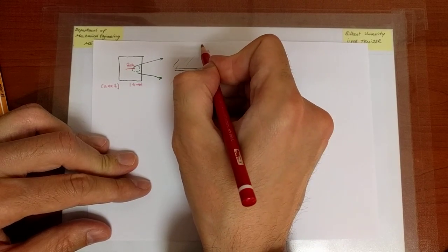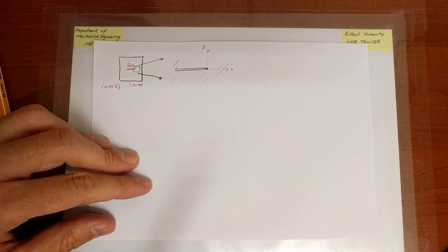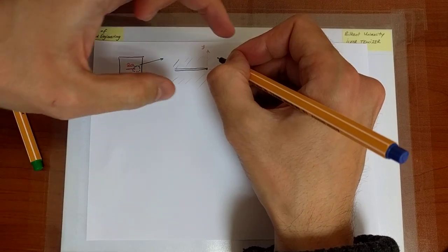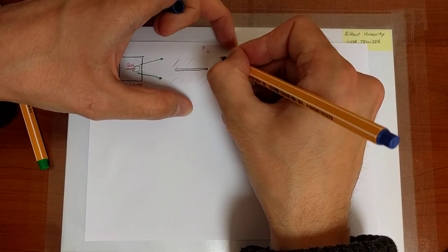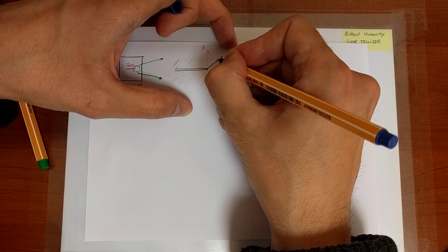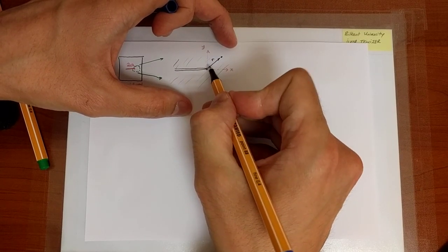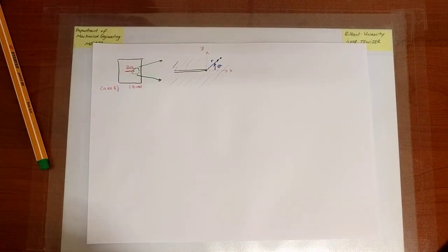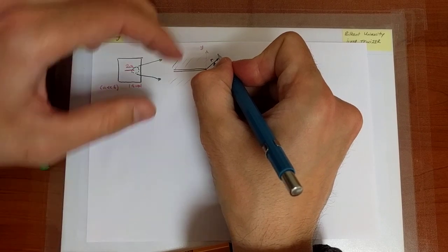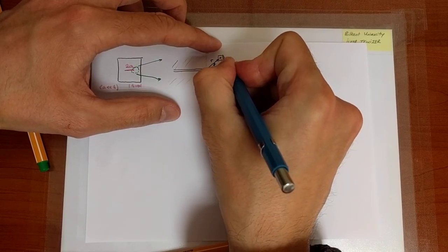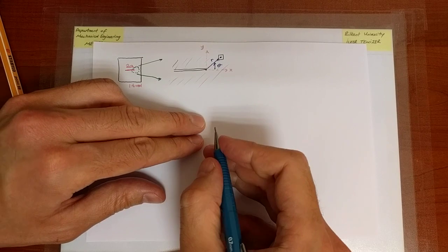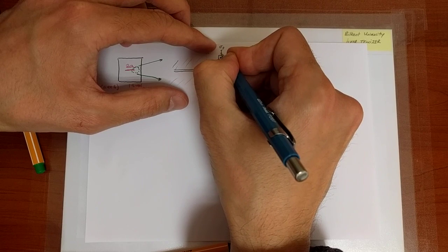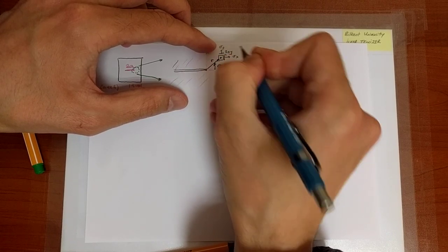But instead of monitoring position in terms of x and y, I will use a cylindrical coordinate system, and I will look at an arbitrary point, let's say located there, and that point will be indicated by a distance from the crack tip, which is r, and an orientation, which is indicated by an angle theta. And now at that point, I will look at an infinitesimal element. I will depict the stress geometrically, and I know that we have a sigma x, we have a sigma y, and ultimately a tau xy.